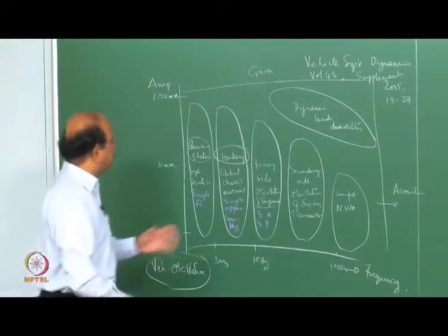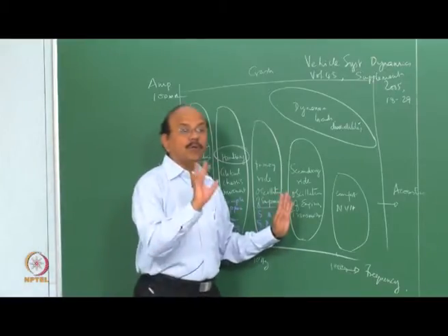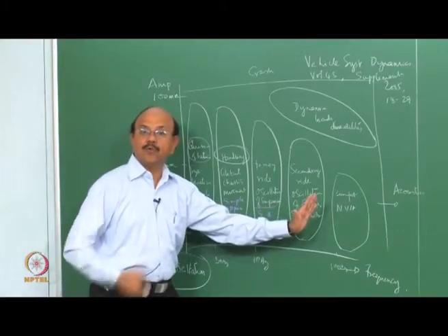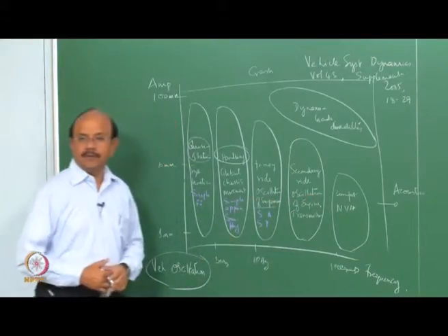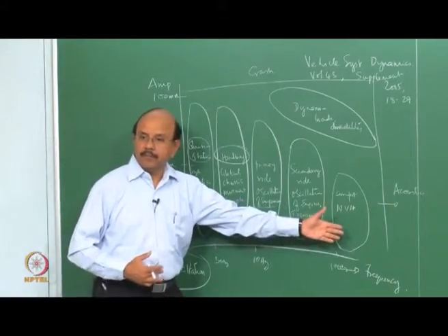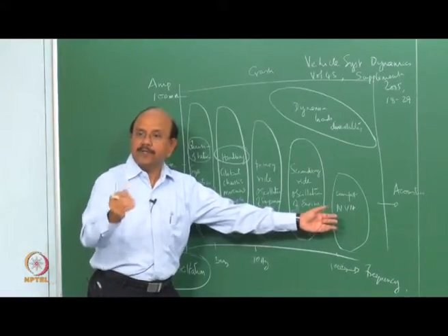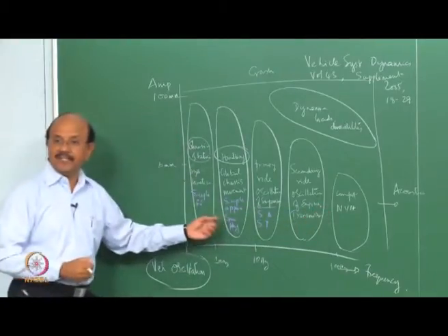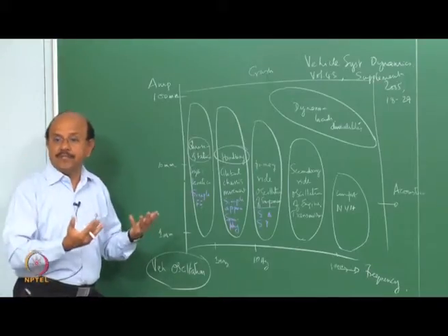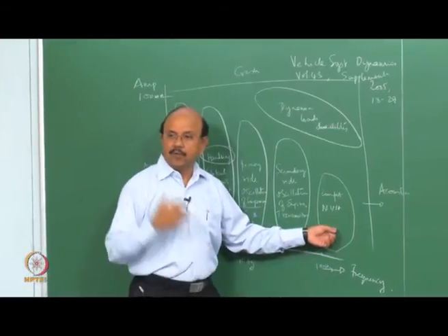Yes, of course. See, the point is this. Is it that I'm neglecting all this? No. What we are saying here is that we look at different frequencies to look at the effects. For example, if I am looking at maneuverability of the vehicle, cornering and so on, the frequency range I am looking at is this. But at the same time, if I'm looking at the NVH, the vibration characteristics, and comfort, for example, I would look at these frequencies.